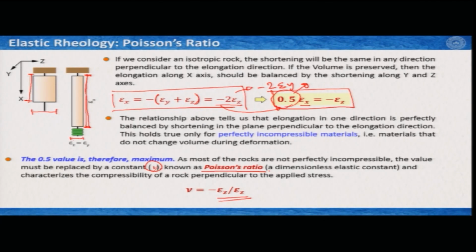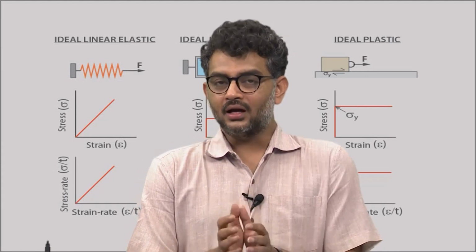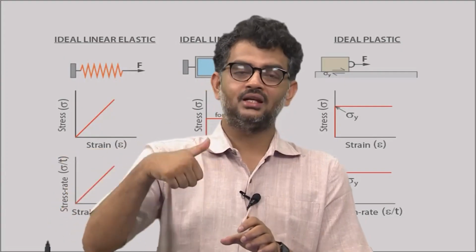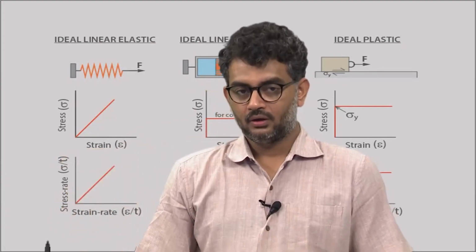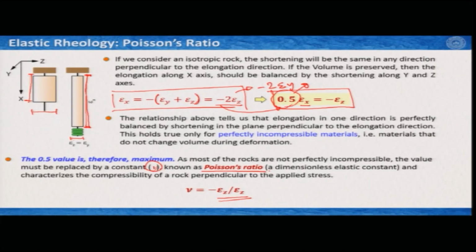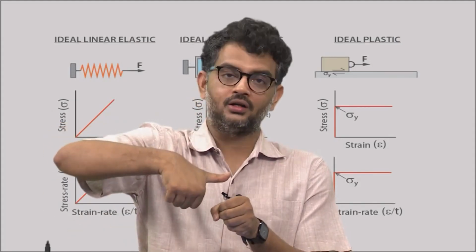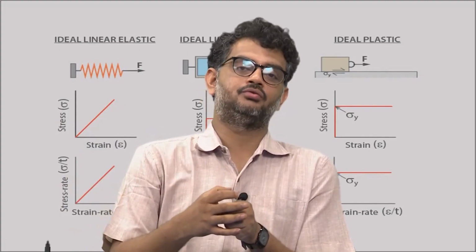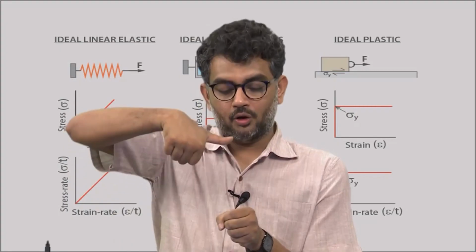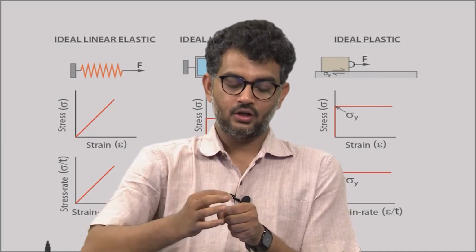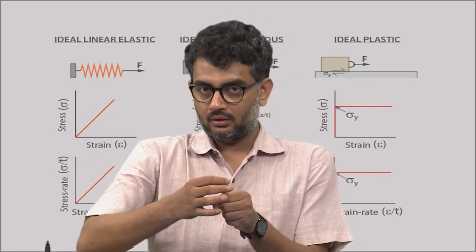Now, I give you a very simple example of Poisson's ratio that we use, that you may have seen in some glass bottles where instead of the caps we use to seal the glass bottles, we use some corks. Now, the corks are very interesting material in the sense that, if you have the bottle and then you have to press the cork inside, because you are pressing, and if the cork has to maintain its volume constant, so you are compressing it this side, so length is shortening on your compression direction, so it has to expand on the other direction.